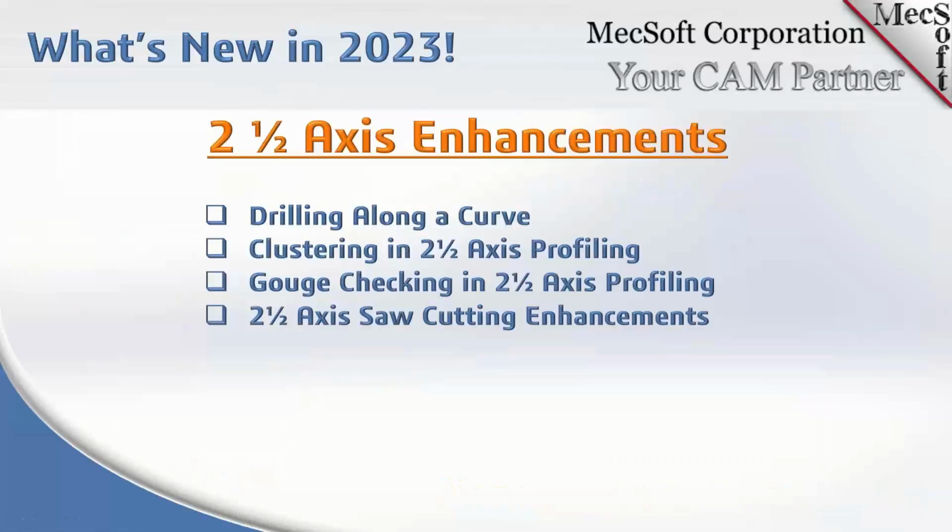Now let's talk about some 2.5-axis enhancements. You're really going to like this one if you drill a lot of holes. We made it a lot easier to drill holes by using a curve only. You don't have to select any points. You don't have to select any geometry other than a curve. And that curve can be a 2D curve or a 3D curve. And this applies to both 2-axis, 3-axis, and 4-axis. So you're going to like that pretty good.